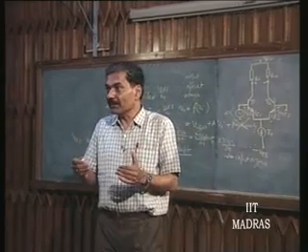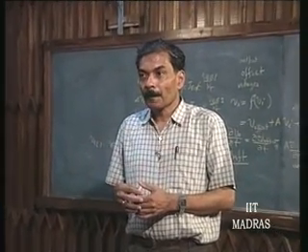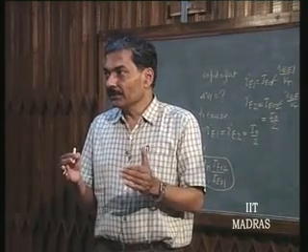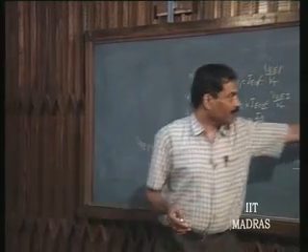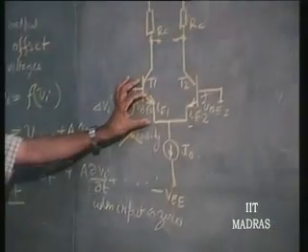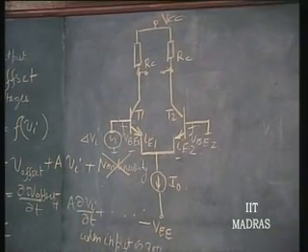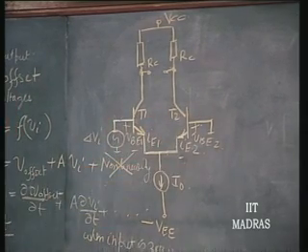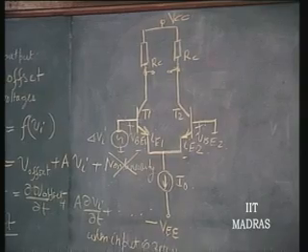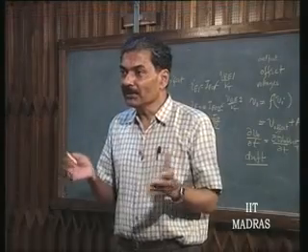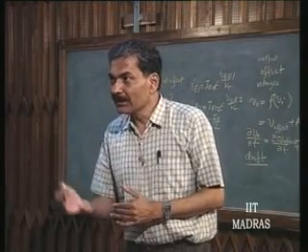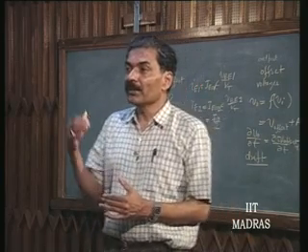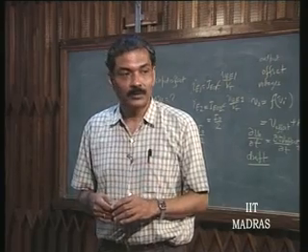In the case of a MOSFET differential amplifier, for example, what is the uncertainty due to? Here VBE is of the order of 0.6 or so, and it is 0.6 for the same current, that means 0.6 here, 0.6 here. It is uncertainty in 0.5 to 0.6, whereas in the case of MOSFET it may be some 1 to 2 volts. So the uncertainty magnitude also increases, in fact by an order of magnitude. It will be of the order of 10 to 20 millivolts.